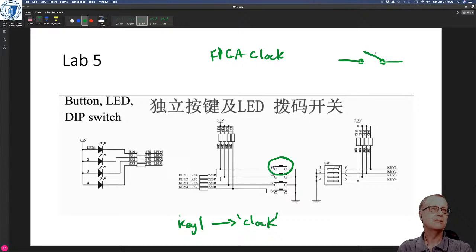However, what's different between a transistor and this switch is that this switch is mechanical, right? And the trouble with a mechanical switch is that when you go from, say, closed to open, if we connected that up to plus 5 volts, and we initially had the switch closed, and then we moved it to open, what we would see here is not 5 volts dropping to 0 volts.